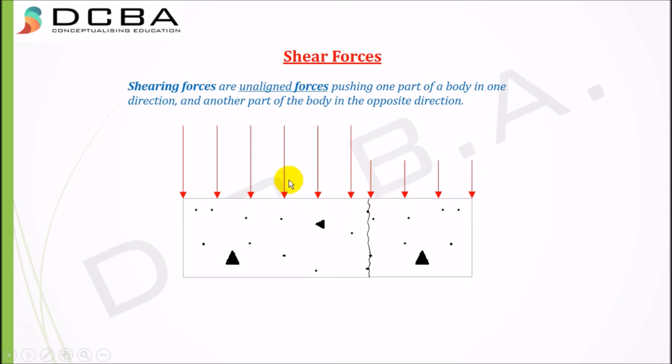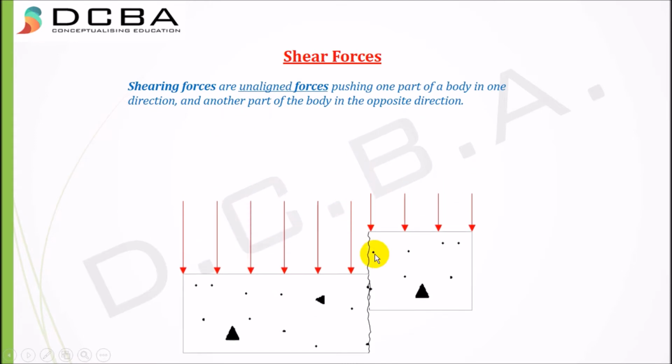And because of this, the deformation of this part of the beam and this part of the beam is also in the same direction, but this part of the beam goes much below than the other one. You can see it in the animation. So you can see again there is a tearing action, and wherever tearing action is there, it is a shear force. Okay, so to give you a fair basic idea, shear force tears your beam apart at a particular section.